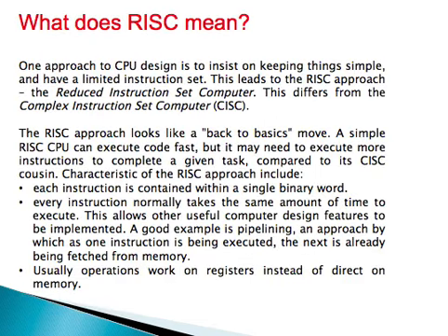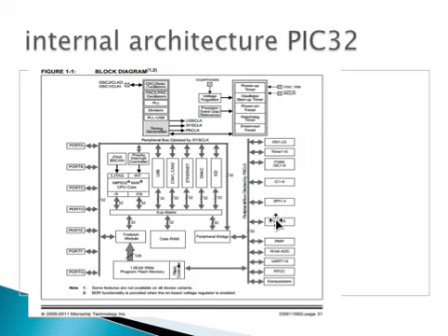So we looked at it. If you look at this one, as I say, the microcontroller has a number of components, and they are all now embedded in one IC. Before, a microprocessor had just the CPU. If you wanted input, output, RAM, ROM, or ports, they were external ICs.